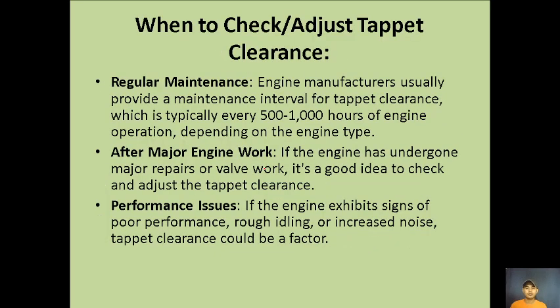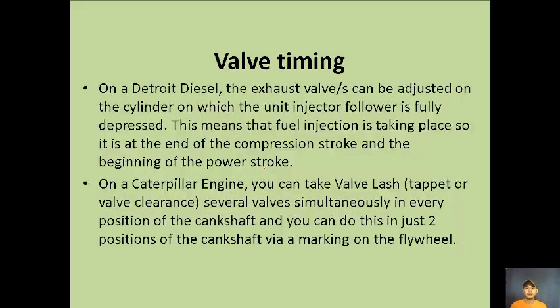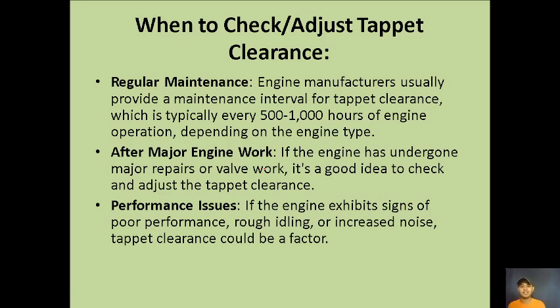Okay, so when to check or adjust tappet clearance? First, during regular maintenance. Engine manufacturers usually provide a maintenance interval for tappet clearance, depending on your manual or on the engine type. Second, after major engine work. If you have done a major repair or valve work, it's a good idea to check and adjust the tappet clearance. Third, during performance issues. If the engine exhibits signs of poor performance, rough idling, or increased noise, tappet clearance should be a factor.